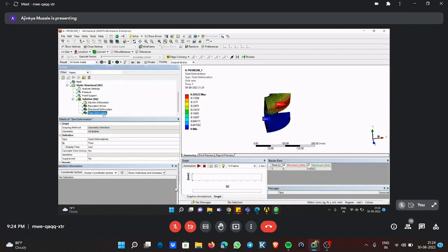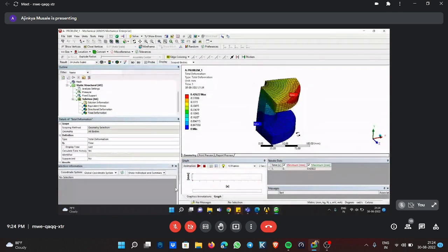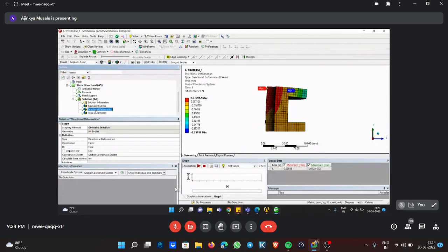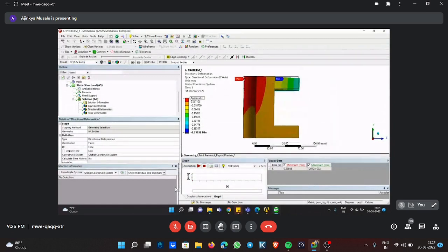So now it's clear what total deformation is, right? At some point you just want to see this deformation, and again, I suggest every time you solve your model, go into the deformation results and make this a model with deformation or undeformed, anything you want. Then I will select some edges and just see an exaggerated view of it, maybe 48 or 24 or 12 times. This is 12 times the actual one.